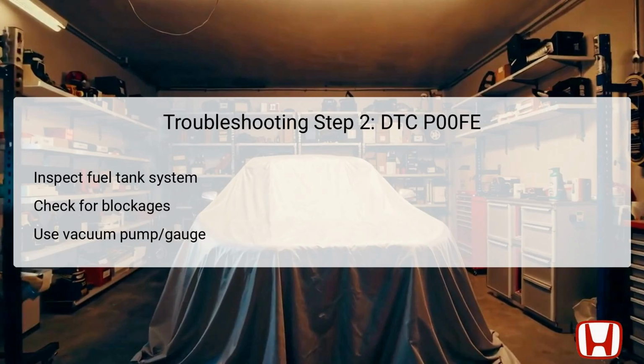By applying pressure to the hose, technicians can determine whether the normal conditions apply, specifically that pressure should not be held. If the system fails to meet this criteria and pressure accumulates, it indicates a blockage within the fuel tank system that must be addressed before further diagnosing the other components.